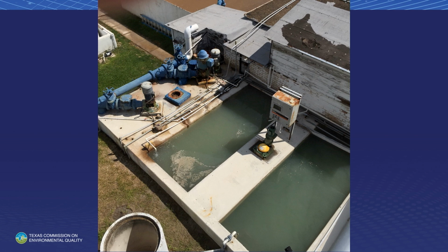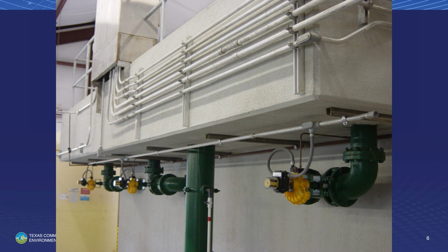Then Noble and I were at a plant. Recognize that, Noble? This is a feeder pipe that comes from the sedimentation basins, and it's feeding a gullet that feeds 3 filters. And that pipe rises up into the bottom of that gullet, and it rises up above the floor of the gullet about, what, a foot, maybe a foot and a half above the floor. And then the water spills out of this pipe and then is distributed in that gullet over to the 3 ports going into the filters.